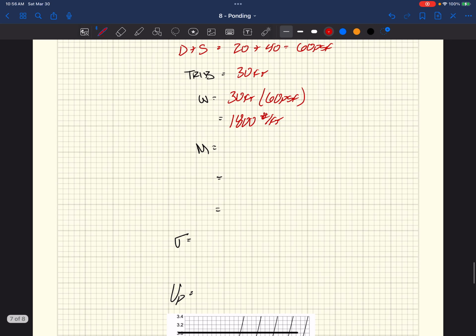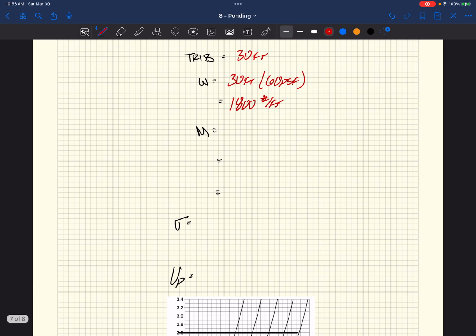Moment: if we assume simply supported members, the moment within our girder is going to be wL squared over 8. Technically, if we have a 40-foot span at 5 feet on center, we really have 7 point loads in the interior of our girder, right?